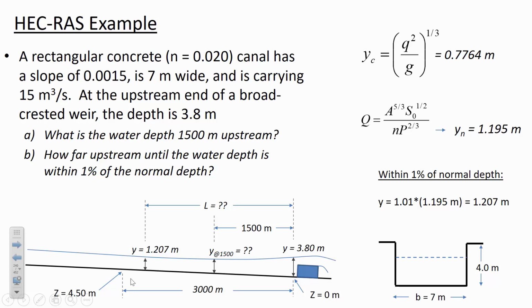Okay, so is everybody with me so far on what the geometry of the channel looks like? Everybody understand what we're trying to figure out with HEC-RAS? We could have done this, and we still could, using the spreadsheet. But the advantage of HEC-RAS is that after we move past this simpler example, it allows you to handle when the channel geometry is changing between segments. So we'll take a look at this easy example to begin with, and then that may inform what it's doing behind the scenes, how it works in the background.